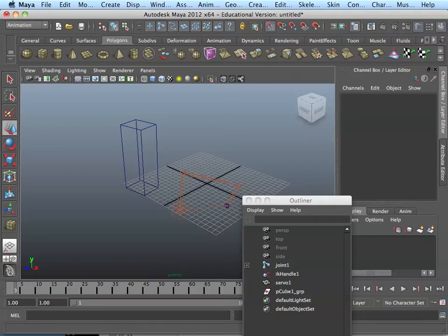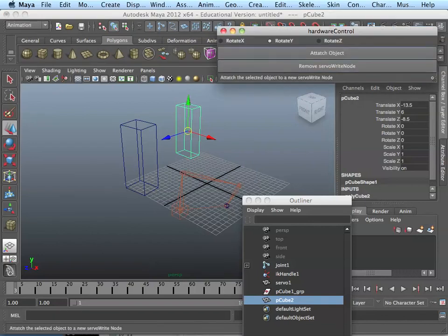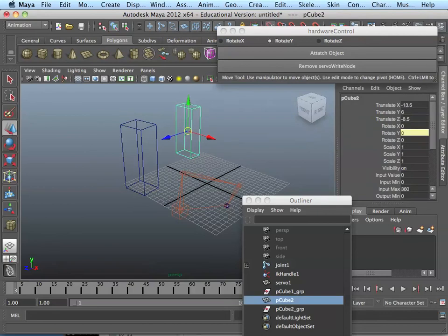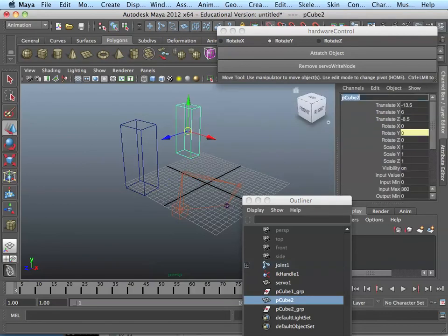And of course, right now you've only done one, and it's kind of pointless to do inverse kinematics with one. But as you might have guessed, today you get additional ones. So you can do the same thing, right? Just say MK servo, rotate Y. That guy is called joint 2. Call him servo 2.